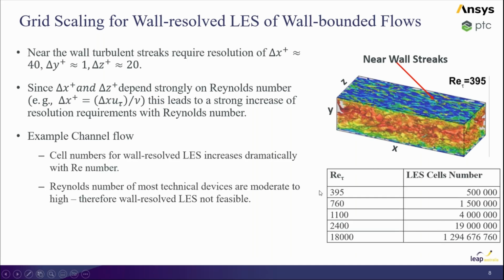So all I want to show you here is that if you choose a Reynolds number based essentially on the friction velocity here, then as this starts to go up a bit, the requirement of cell size, its number of cells to integrate to the wall, explodes and becomes completely and totally impractical. So you can see immediately why we just don't recommend this.